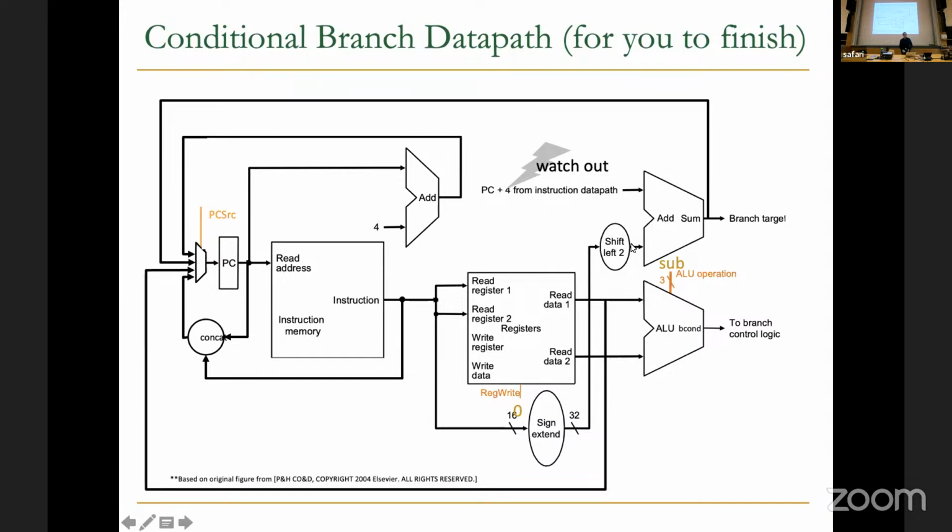We need to add a special adder for this, as you can see, right? Why? Because we're using the ALU to do something else, right? Okay, so now we have 3 types of adders in our system. And that's going to be one of the disadvantages of single cycle logic also. MultiCycle can be more frugal in this sense, and we will see that. Okay, so that's going to be input to this increasingly complicated multiplexer in front of the program counter because it needs to support different types of branches.